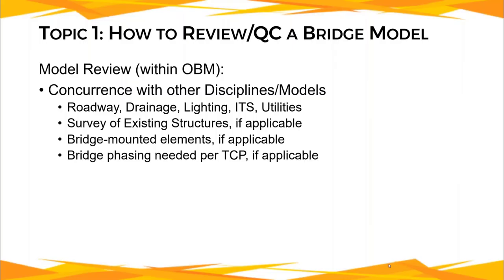for a bridge. But other things that you want to take a look at, obviously, are any survey of existing structures, if around. That's important, and how it relates to the proposed bridge. Take a look at bridge-mounted elements, if applicable. Sometimes we model the light pole pedestals on bridges.